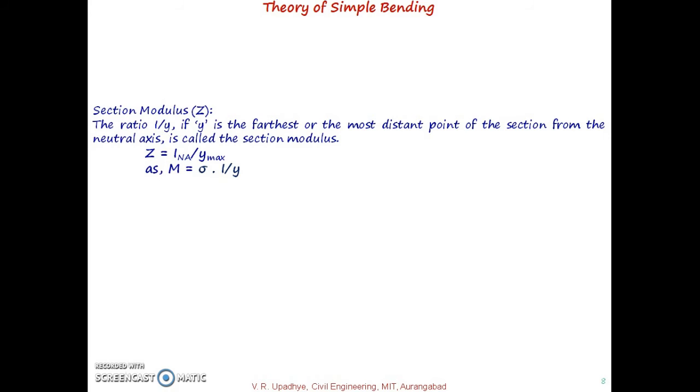And one more term is M is equal to sigma into I divided by y. So if we consider Z, the section modulus, then maximum stress will be M divided by Z. So sigma max, the maximum stress, will be M divided by the section modulus Z.